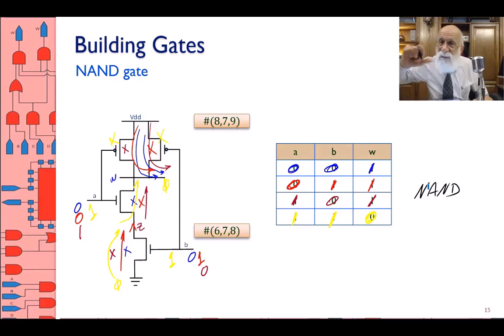There are transitional situations, where the pull-up is trying to push a 1 and the pull down hasn't released the 0 yet. And therefore you have a short period of time that both of them are conducting, or a short period of time that none of them are conducting, just like the inverter.